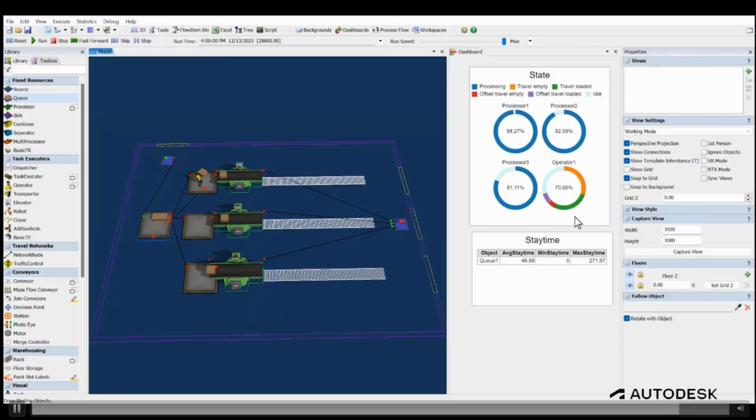In the first example, we lowered the utilization of the processors to lower the wait time in the queue. In the second example, we raised the utilization of the processors by eliminating the effective travel time to lower the wait in the queue. Utilization plays a vital role in the optimization of any manufacturing, material handling, or process system. Simulation plays a vital role in understanding utilization and the tug-of-war the 3 types of waiting times have on the cost of the process.